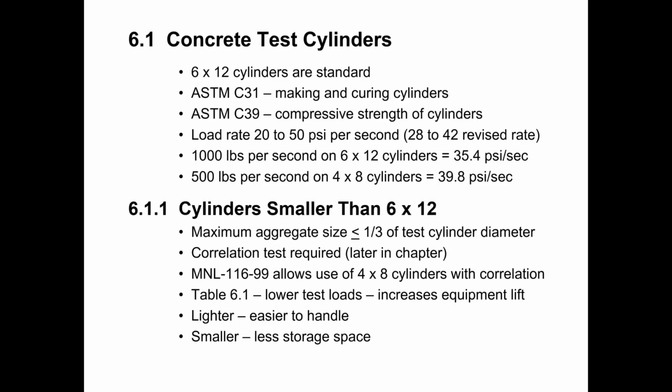Also, they take up less room in the storage area, whether we're using a 100% humidity room or we have a tank that we're storing our cylinders in. We can get a lot more 4x8 cylinders in the same space than we can 6x12 cylinders. So storage space is also an advantage to using 4x8 cylinders.